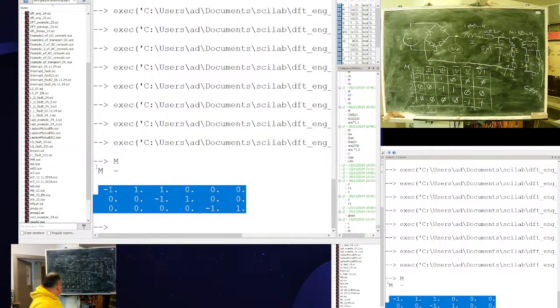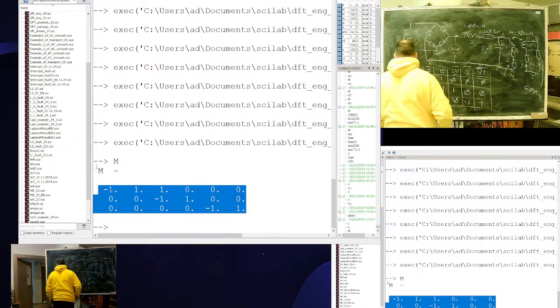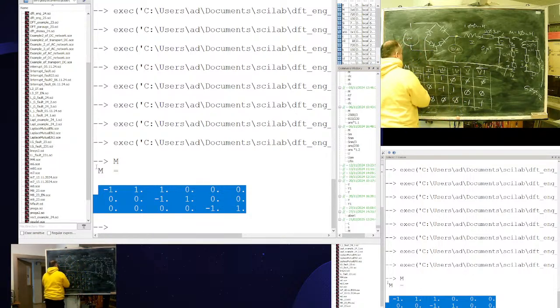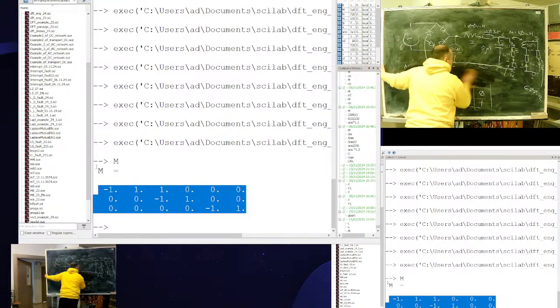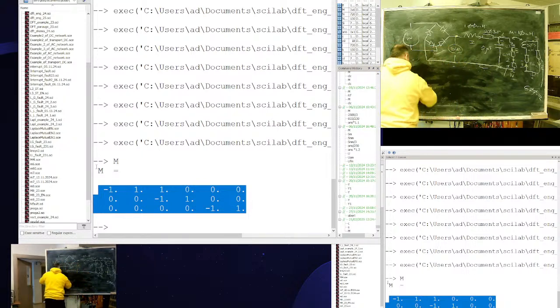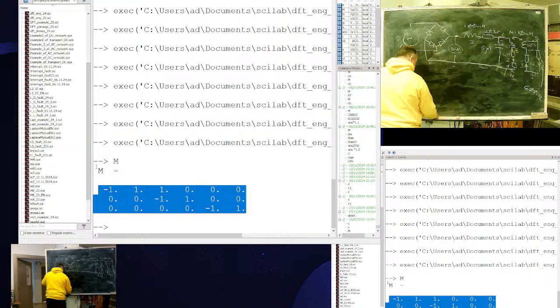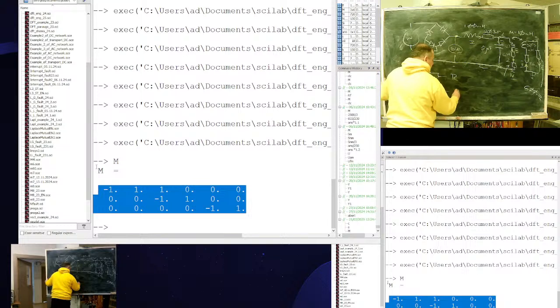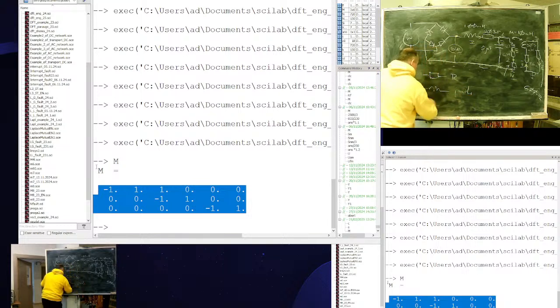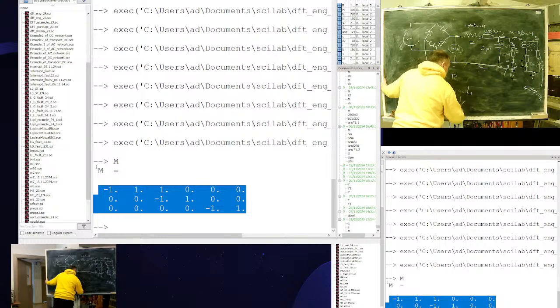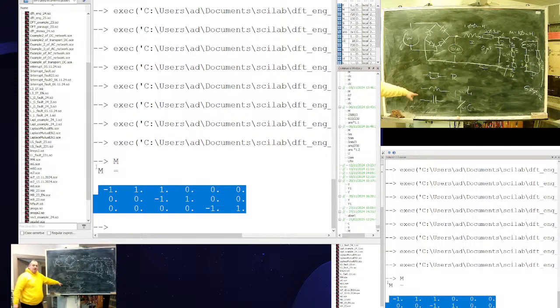First, I will use a small vector. I need to fill a special matrix. The main diagonal forms the branches' self-impedance. For resistance it will be R. For a coil, j omega L. And for capacitors, 1 divided by j omega C. Yeah, it's from electrotechnics theory.